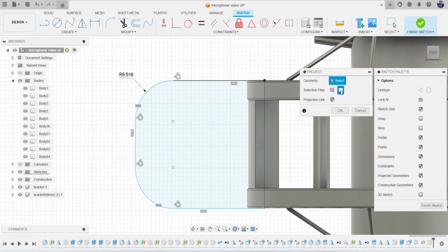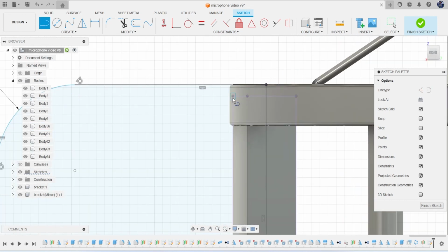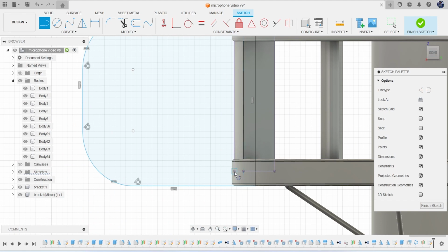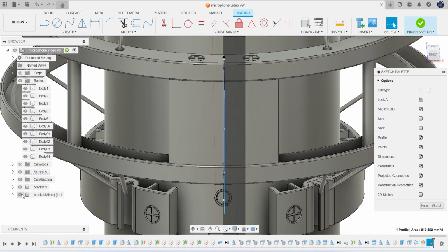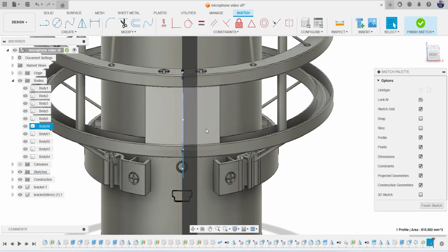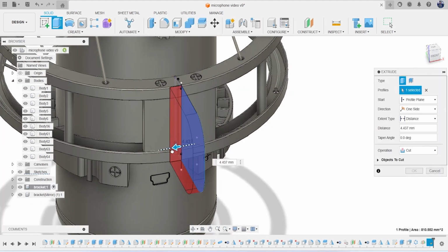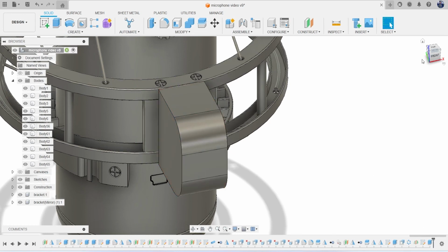Come out up there, and let's fit it to these edges to round it off a little bit. Hit P to project to grab that profile as well. And line and just extend it up. Like that. So I can grab this profile. I'm actually going to turn nothing off at the second. Let's wait until I've done a bit more first. Let's then do symmetric, new body.